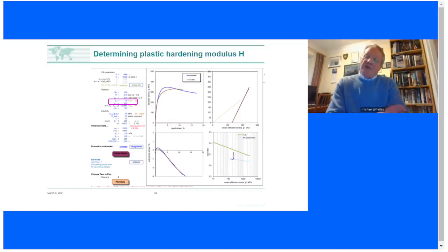One property I haven't taught you about is stiffness. If you look at the equations on the hardening law, there's a property H involved. You can think of this property H as kind of an initial stiffness in a triaxial test. We don't like doing that because, in fact, H appears everywhere throughout the whole evolution of the soil behavior.